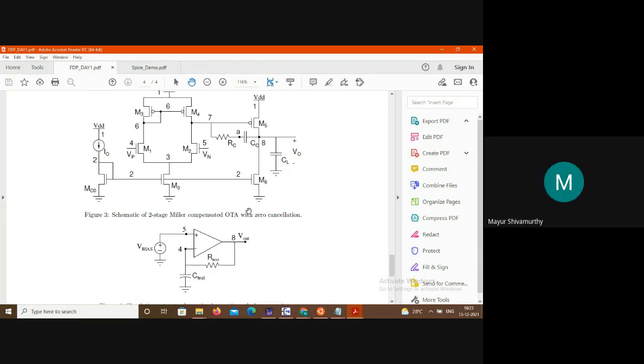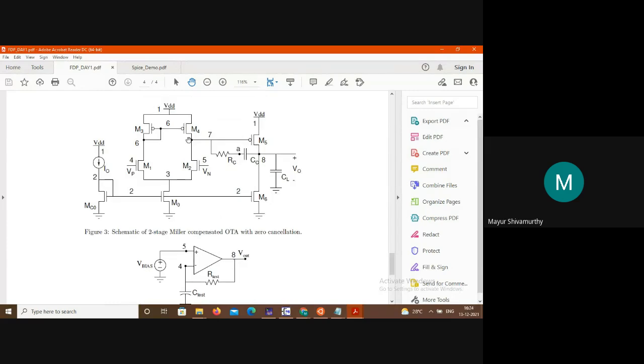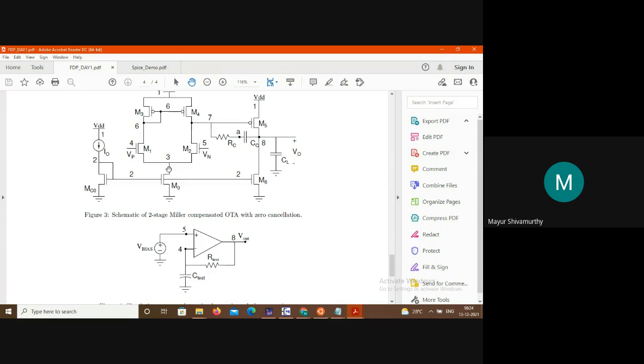Okay. For the simulation, it's very important to have this simulation setup, because the DC operating point in this two-stage op-amp is at a defined point only if there is negative feedback. In order to ensure the negative feedback for DC, we'll put a large resistor and a large capacitor. In case of DC, this feedback is established, and when we are doing AC analysis, this feedback is broken.